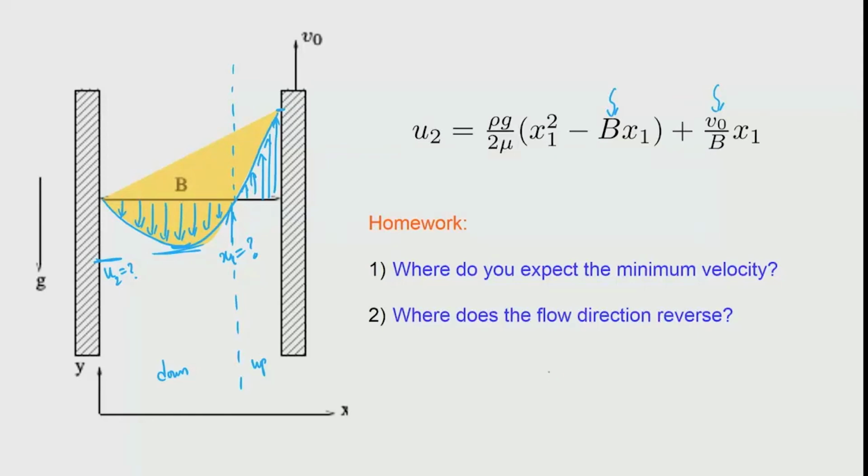So, basically we are looking at solutions that are coming from only the diffusion term, okay, and only one at a time, and we are then getting the solutions in a simple form, and you can see that the solution is applicable to the entire domain. Okay. And this is something that we are going to relook later on, whether this is reasonable or not. But at this moment the diffusion profile is applicable to the entire domain, and that requires the laminar assumption to be valid, and that is the reason why we want to look at the critical Reynolds number, so that the solution is valid.